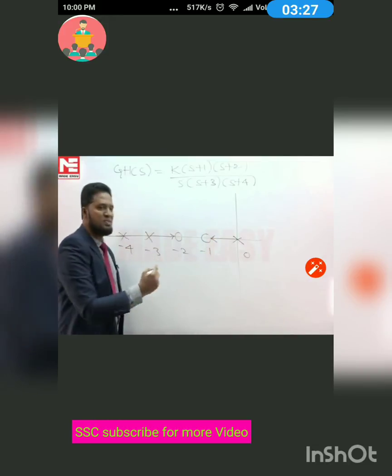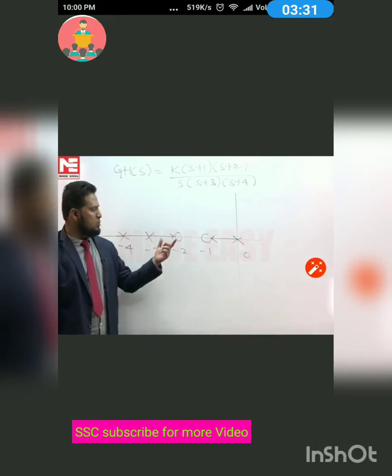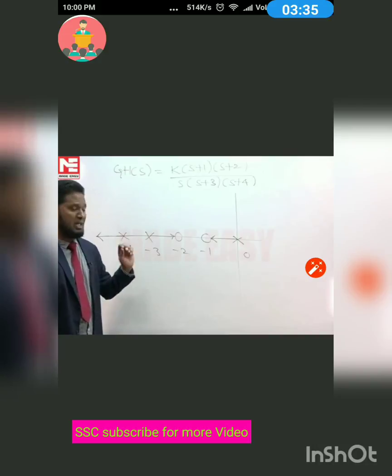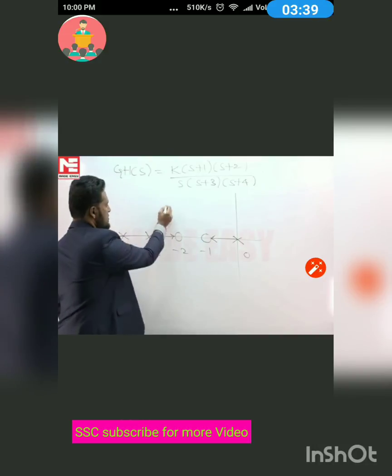This is the root locus of the system. For any value of K from 0 to infinity, the roots of the characteristic equation, called closed loop poles, are found to be real and unequal. They are real but unequal. So the answer to the question is real and unequal.